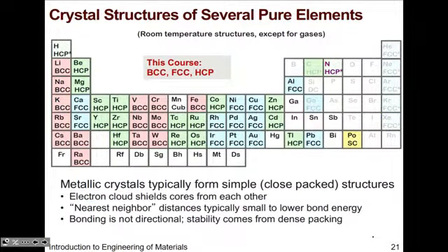Right, so I've gone over these specific examples, and I've summarized here why we should care about them. So you have BCC, FCC, HCP. These are relevant crystal systems for broad-based systems for the elements that you interact with every day. Those are highlighted in the different colors that you see here, in blue, pink, and green. So you can just take a look. Obviously, you don't have to commit everything to memory, but you definitely should know, when given a Bravais system, how you should treat it, how you count coordination numbers, and how you can relate the lattice parameter to the atomic radius.